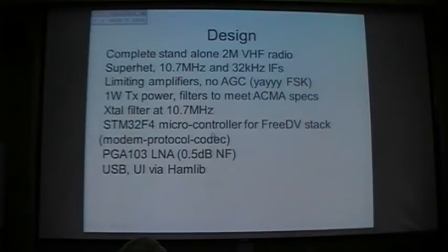It's got a PGA103 LNA, it's got quite a low noise figure. I think the overall noise figure in the radio is around 1 dB or 1.2 dB. We need that as we're shooting for this very low minimum detectable signal.